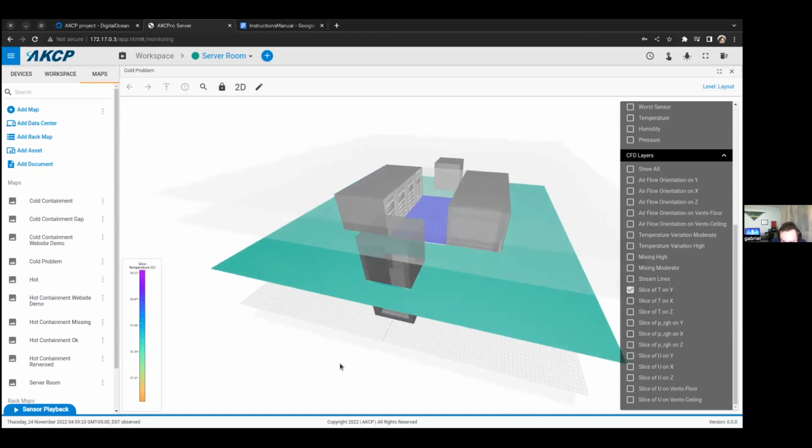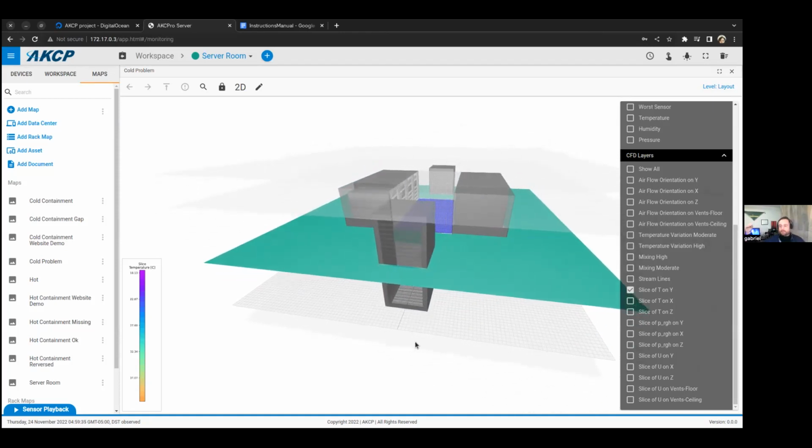The air comes from the crack and the model tried to compute where the heat goes, and it cannot find it. So it creates a space with a really high temperature, and the model crashed. So when that happens, you can see it.